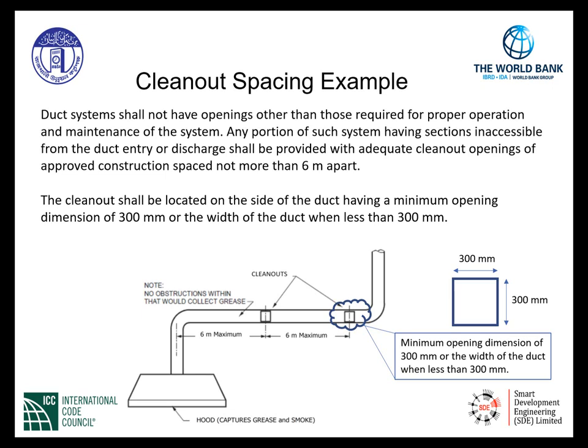A little detail indicates the minimum opening dimension of 300 millimeters or the width of the duct when less than 300 millimeters. If the duct is of adequate size, the duct cleanout opening will be a minimum of 300 millimeters by 300 millimeters.